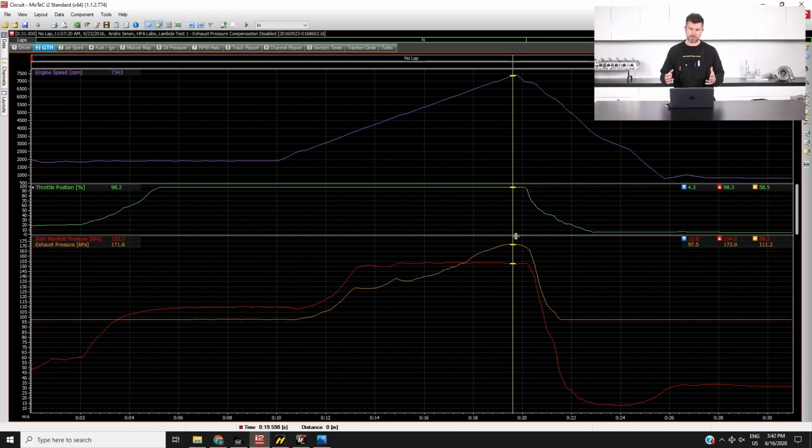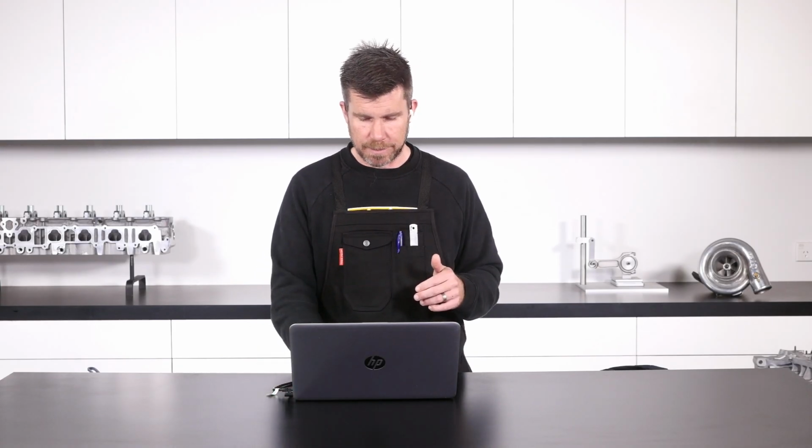But as we're going to get into in a second, it is also possible to use the exhaust manifold back pressure signal as part of an actual load calculation in some ECUs. Now, if you want to do that, you're definitely going to need a smoother signal than that raw one, otherwise you're going to have problems. A variety of ways of doing this. It can be dealt with in the software itself. It can be smoothed or filtered internally, but I've found the easiest solution is just to do this mechanically with the damper. So let's head back to our photos here.